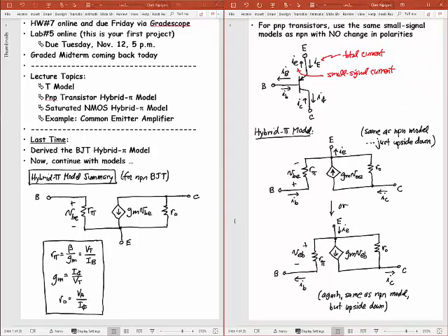So you might want to think of the currents going downwards, because usually for a PNP transistor, usually for any circuit we draw, like I've said in previous lectures, the top is going to be the higher voltage. The bottom will be the lower voltage. So currents will always want to flow down the way that we draw these things. Okay, so if I'm doing this, it looks like the currents are going up, which they can if they're small signal currents. The large signal currents will want to go down. The small signal currents can go up and down, either way.